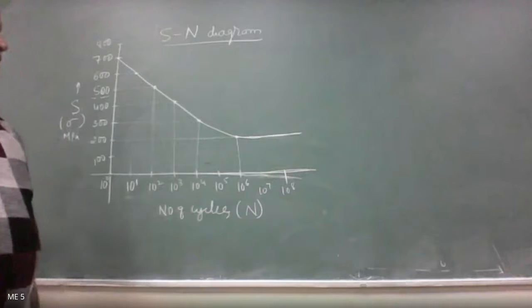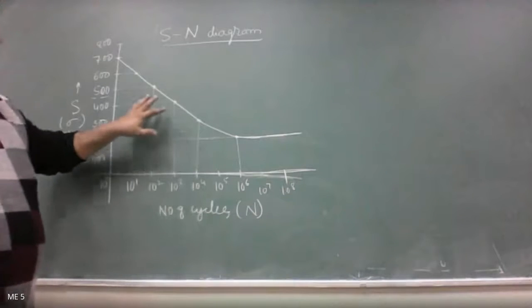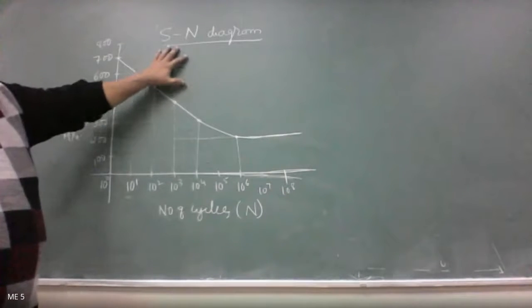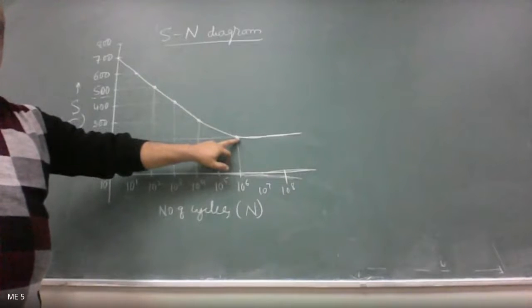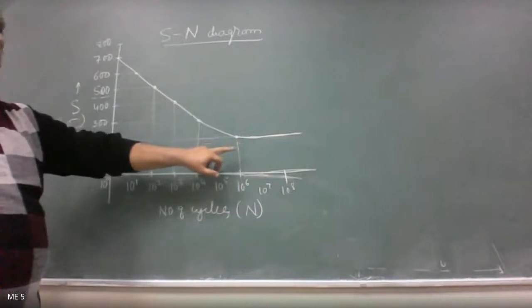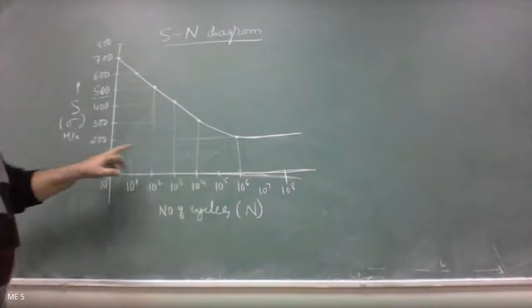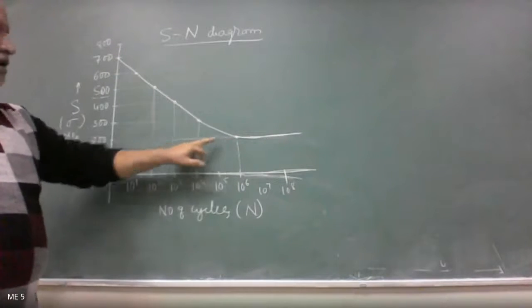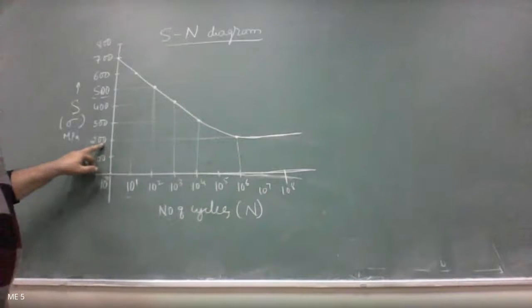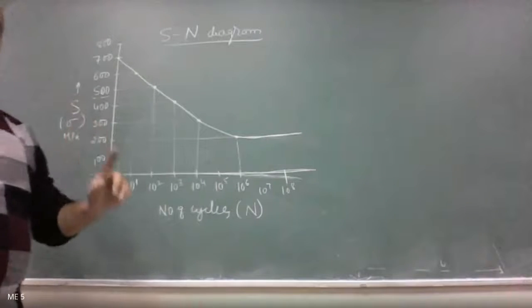Parallel to the x-axis, rather. Okay. So this is what is called an SN diagram. What is the fatigue stress of the material that I have chosen? It is 200 megapascal, because what is the definition of fatigue stress?